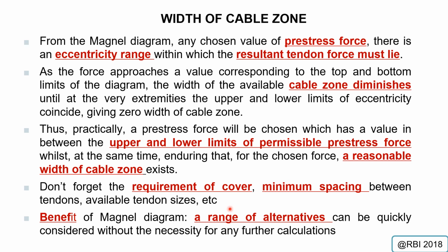Okay, so you could also conclude that the Magnel diagram will give you a range of alternatives that can be quickly considered without the necessity of any further calculation, because you can simply plot it in the diagram itself, in terms of knowing the range of e that you want to use and the respective pre-stress force that you want to apply.